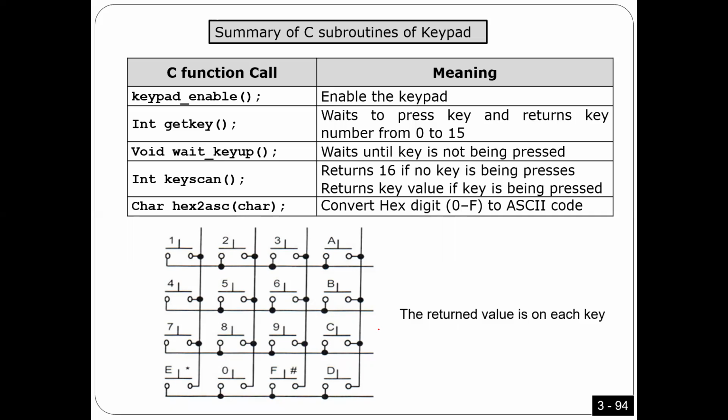Sure. How do you get the return value from the keypad subroutine? In register A. All you have to do is jump subroutine keypad, and after keypad it's already in register A. And that's what we are going to do in lab.